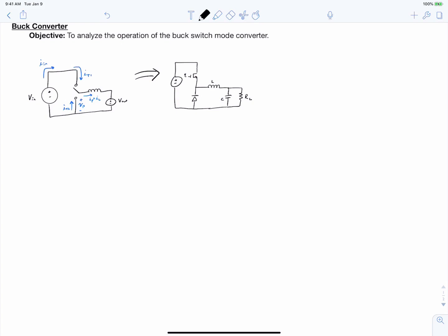And you'll see that in this circuit, I've labeled the gate signal for the MOSFET as Q, and I've added a capacitor and a load resistor. So the capacitor is going to be considered a little bit more towards the end, but this is the practical implementation, is that we have a capacitor here that we can model as an equivalent voltage source. And then we're modeling our load this time as an equivalent resistor, which has a value of R sub L.